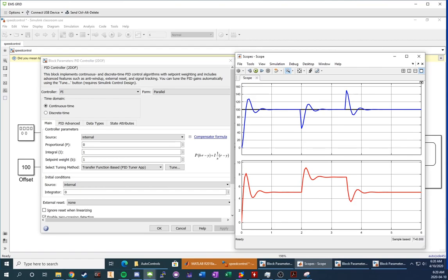Finally, we're moving on to the ability for a PI controller to do the same thing. So setting the proportional controller gain to 0.1 and then the KI to 1, DSP to 1 as well. We can go back and observe the response for that. Take some notes, take a screenshot, and sort of recognize what's happening. You might want to look at the speed that it responds with, take some measurements. The important thing is that you can see what happens when you adjust these parameters. What happens when you increase or decrease the proportional gain.